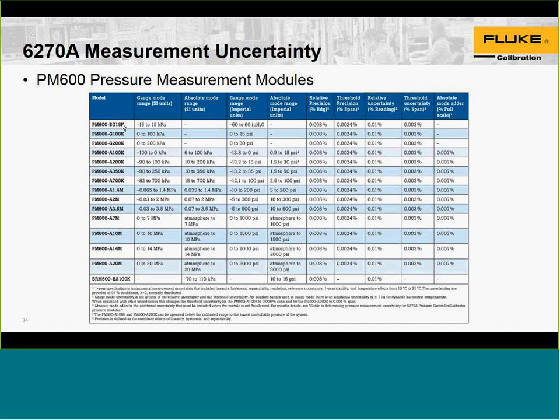Typically for controlling low differential, including negative pressures, in addition to a low pressure supply, there'll also be a vacuum pump attachment, attached to the supply to the controller, so that the controller can tune in between that vacuum value, the negative gauge value, and the pressure.